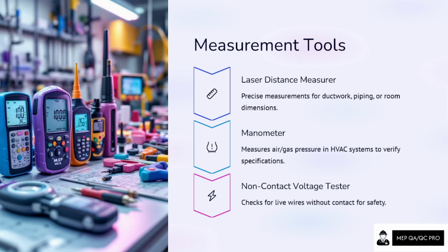Manometer. We use the manometer especially during testing and commissioning of the HVAC system, where you have to measure air and gas pressure. Everything you can identify through the manometer.